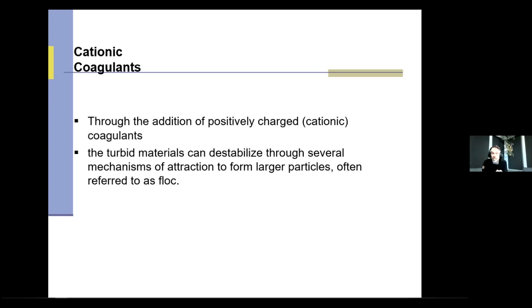snowballs, they look like snowflakes almost, of product, right? All these little colloids are going to be sticking together with the coagulant and creating a floc, something that's heavy that I can remove. This word cationic means positive, and we can also buy anionic, and that's a negatively charged coagulant. So sometimes that's used as well, depending on the type of product. Understanding if you're getting rid of color and organics, which most of us will be in our treatment processes, that is what's needed.